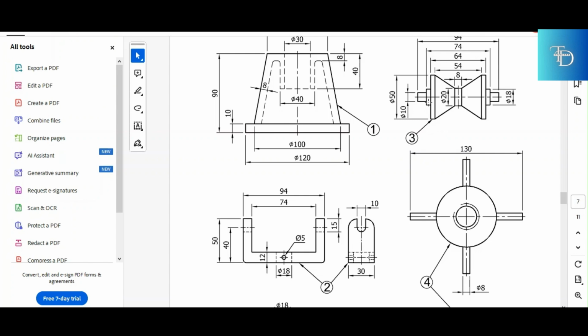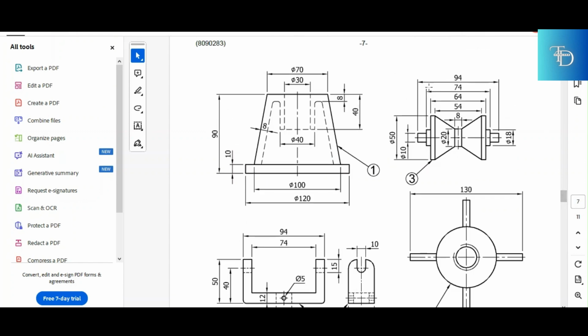So this roller sits with the left hand side of it on the left hand side of the roller cradle, and then it sits with what? With the right hand side on the right hand side of the roller cradle. So how long is it? It's 94 millimeters long, which is the maximum length. How long is the roller cradle? 94 millimeters. So you see the what? The connection, the relation right there. This is how you search for connections. Even if you don't know what is going on, you don't know the part, you've never seen that mechanism before, it doesn't matter. You just search with the dimensions, and then you get to be able to solve the whole thing.